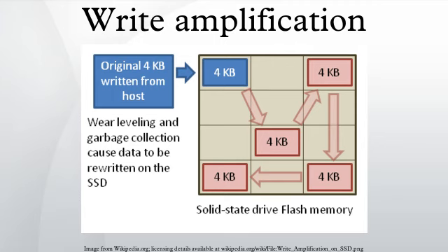During this phase the write amplification will be the best it can ever be for random writes and will be approaching 1. Once the blocks are all written once, garbage collection will begin and the performance will be gated by the speed and efficiency of that process. Write amplification in this phase will increase to the highest levels the drive will experience.